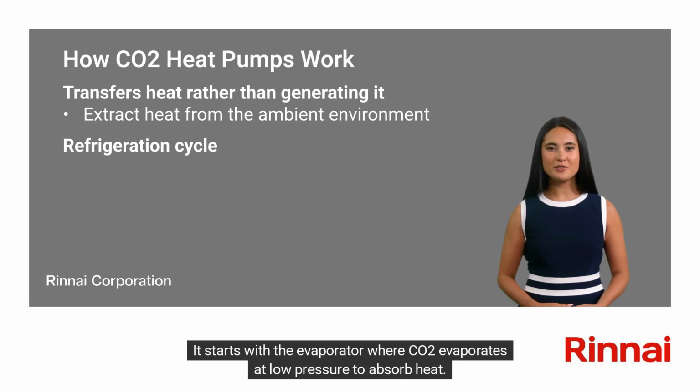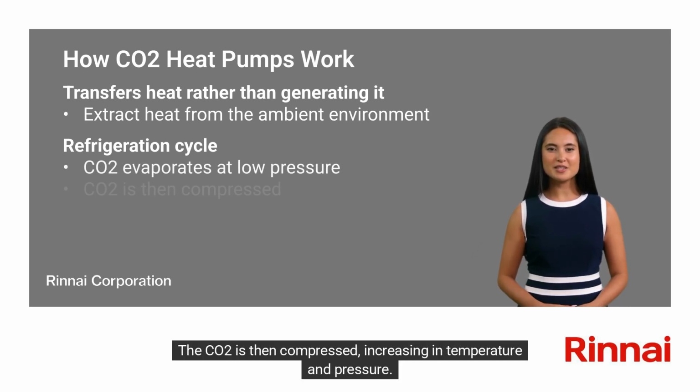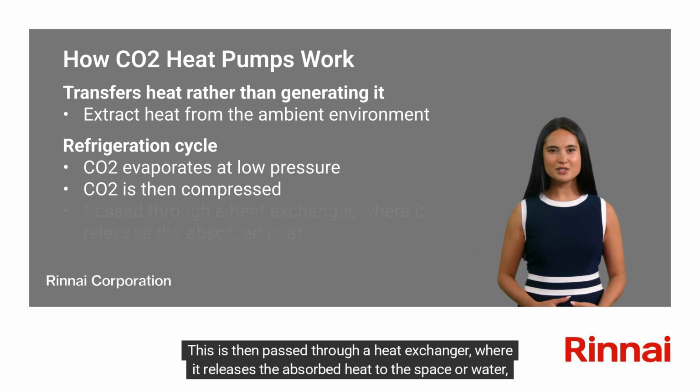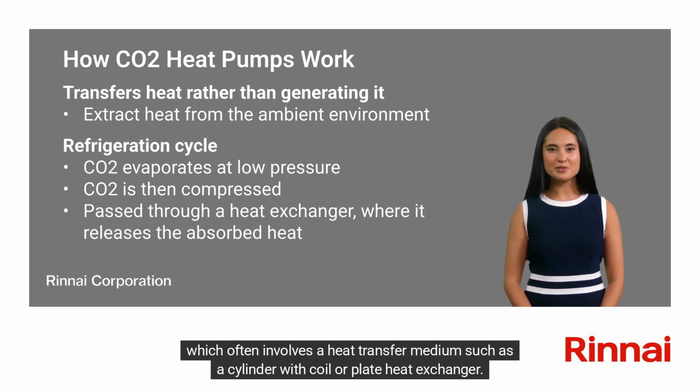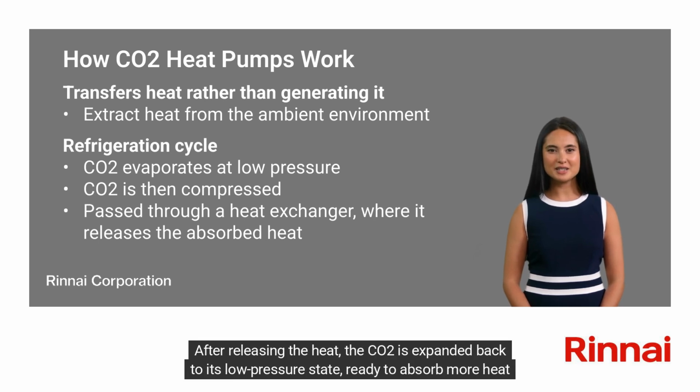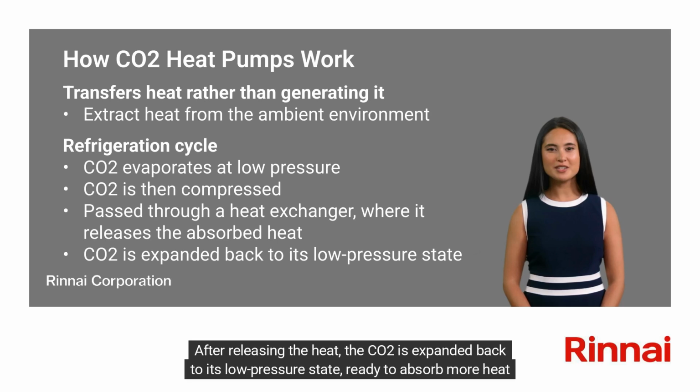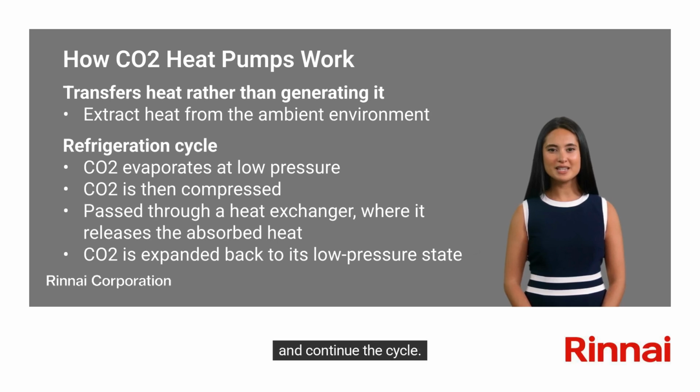It starts with the evaporator, where CO2 evaporates at low pressure to absorb heat. The CO2 is then compressed, increasing in temperature and pressure. This is then passed through a heat exchanger, where it releases the absorbed heat to the space or water, which often involves a heat transfer medium such as a cylinder with coil or plate heat exchanger. After releasing the heat, the CO2 is expanded back to its low pressure state, ready to absorb more heat and continue the cycle.